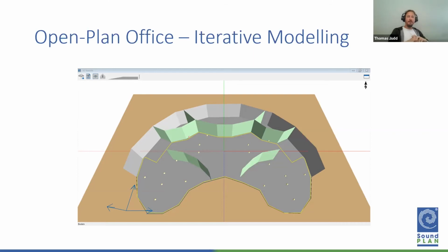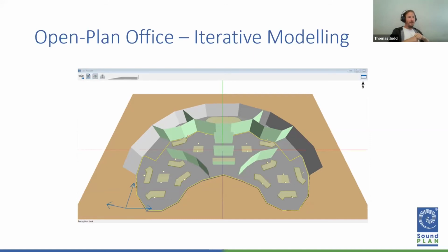And having done that, you wind your simulation up and you let it run and you see what the parameters are doing. So reverb times, speech intelligibility levels, that sort of thing. And having done that and got your reference, you then think about, okay, what are the most acoustically relevant objects, typically judged on the basis of equivalent absorption area. And so let's put those in, and then we rerun and see what effect that had on the room acoustic parameters, and see how much they've changed.